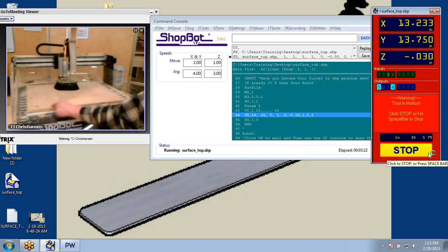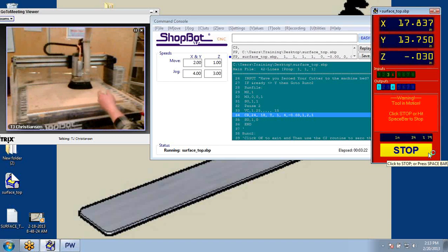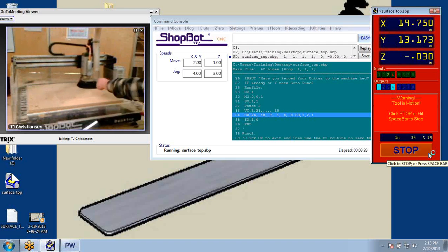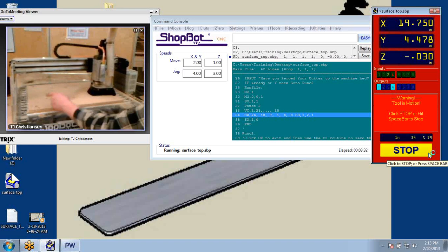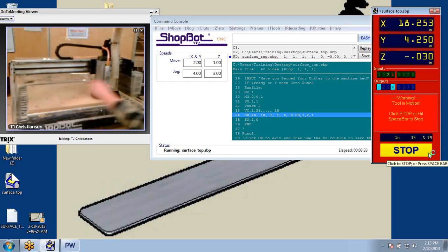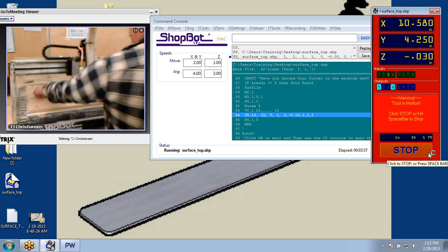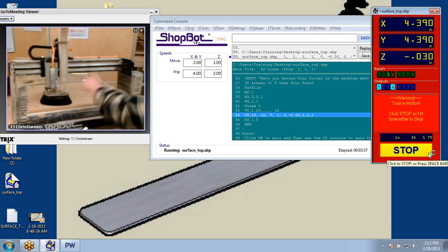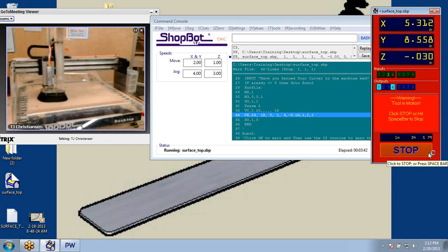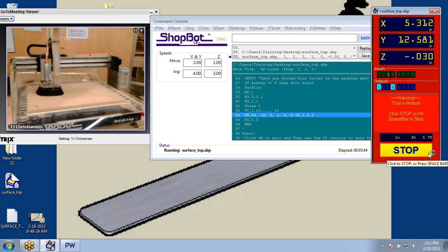I want to make it run quicker. So notice on this, it stops, comes forward, stops, comes forward, stops, comes forward. It's 4 different moves. Where if you don't have it stopping to go this way, I just have it going back, forth, back, forth, back, forth. It's a lot less stops. So on a full 4-foot by 8-foot sheet, it won't take as long.